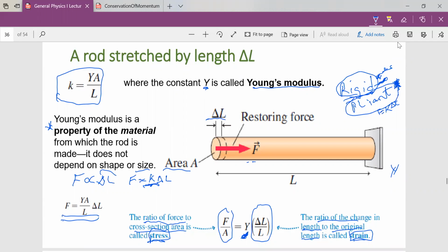Another thing to note here is the longer the rod, the better it is to see the stretch and strain. Because if it's going to take about 16,000 Newton to get a stretch of just 0.101 meters, you know what that means. If you reduce the size, you will have a stretch that is negligible, that you cannot even notice.